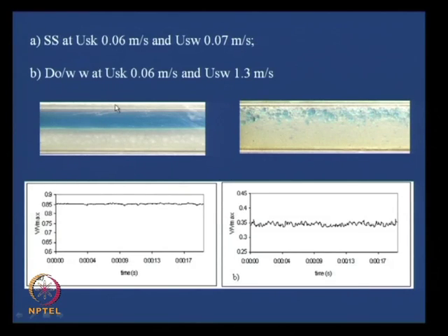Okay. So, therefore, you just see, when it was stratified flow, see here, large amount of kerosene is here, here small amount of kerosene is there. For large amount of kerosene, we had got a higher voltage value. Sorry, here less amount of water, large amount of kerosene, correct. So, therefore, we got a higher voltage value. The moment we had larger amount of water, we had a lower voltage value.